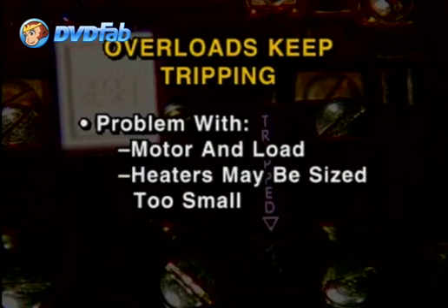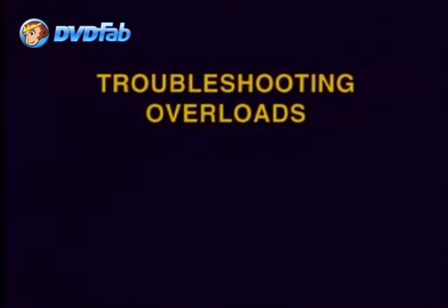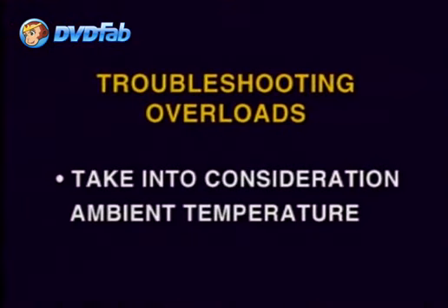If the overloads keep tripping, you may have a problem with the motor and load, which should be checked, or the heaters may be sized too small, thus making the motor trip the overloads frequently. The overloads must be sized according to the motor's manufacturer and the starter's manufacturer specifications and the rules of Article 430 of the NEC. When troubleshooting the overloads, you should take into consideration the ambient temperature at the starter and at the motor.